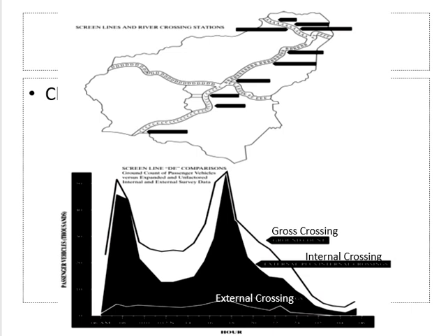They are just crossing, but they are not starting or ending their trip in these two zones. Somebody came from here, outside your zone. He crossed the screen line, but he is not from these two zones. Okay, so somebody started from here, he crossed, but he did not stop here. He crossed another zone as well, he was going somewhere else. Okay, so those trips are part of external crossing.